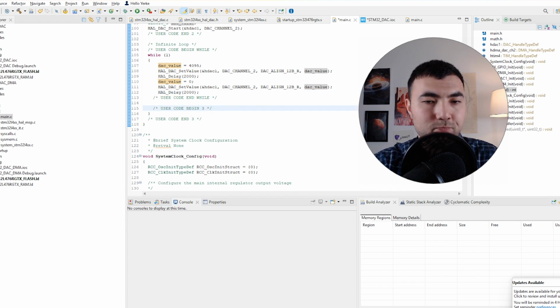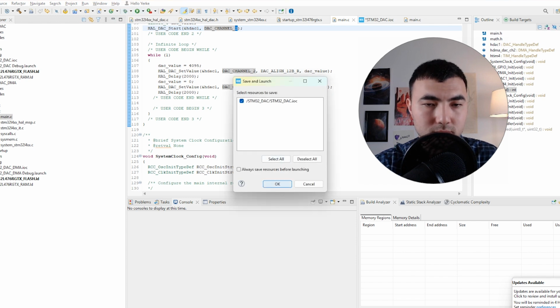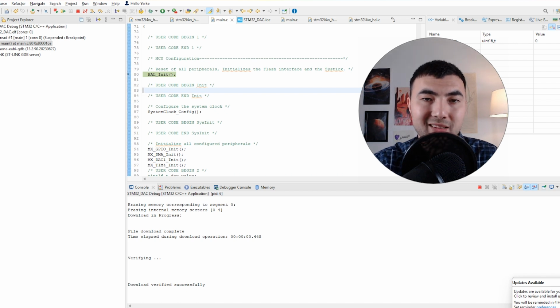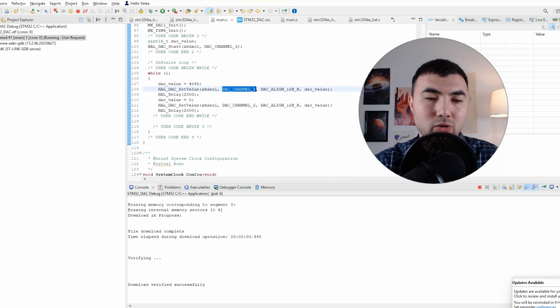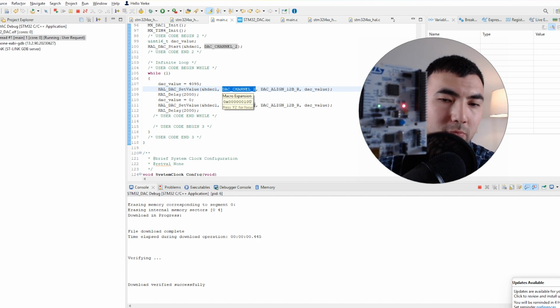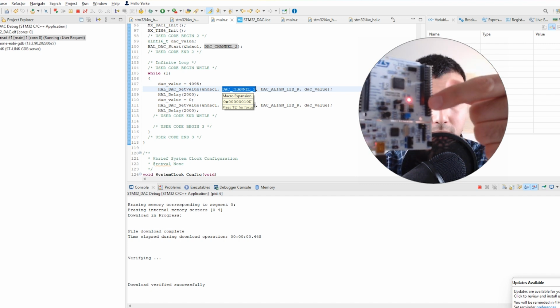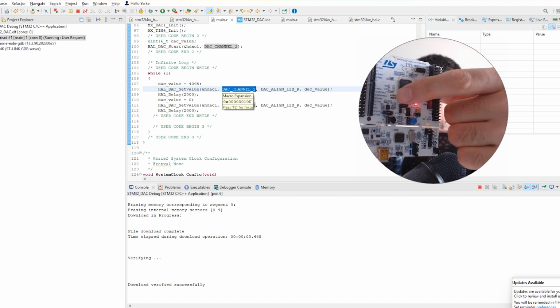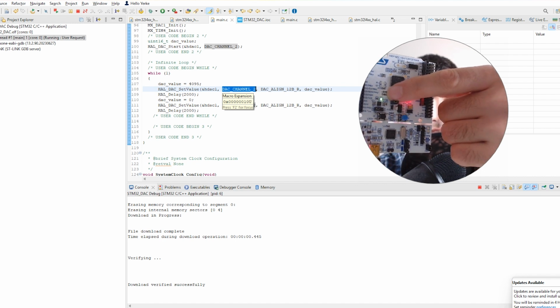Next, of course, we need to debug, just to show how things work there. I'm going to open the debug perspective. Right now I'm in the debug perspective. I resume the code, and as I said, channel 2 is connected to the LED on my microcontroller board. Hopefully you can see this green LED just over there. It is blinking with a 2-second delay.